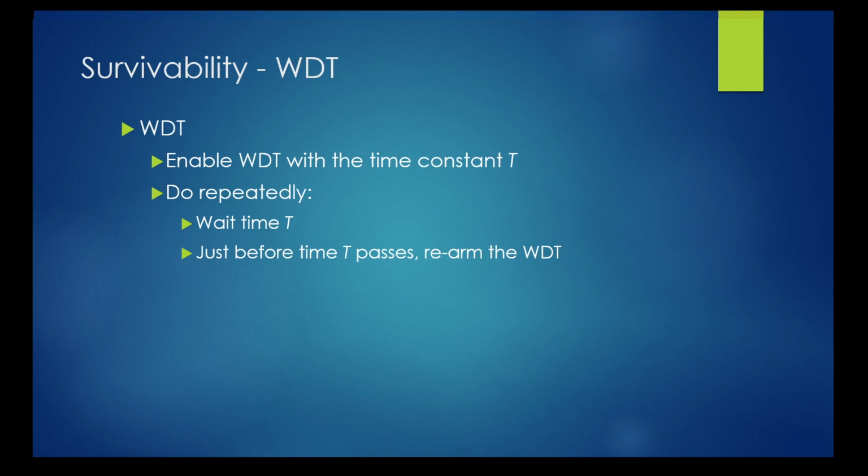One way to manage the rearm actions is to make it the responsibility of a thread that is assumed to get a time slice at least every t time. The assumption is that if the system is hung, the thread will not get to run and will miss the t time window. Of course, this scheme is true only with a careful design, and of course there are other ways to try and detect hangs depending on the overall design. This is just an example.